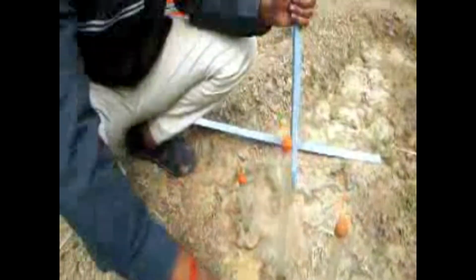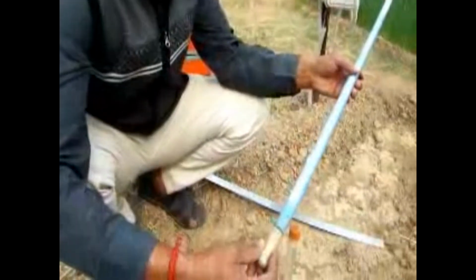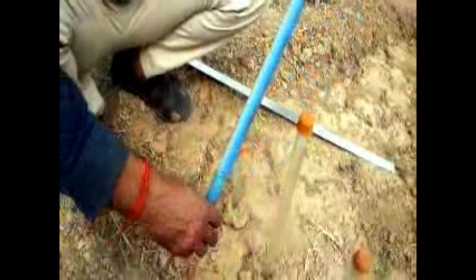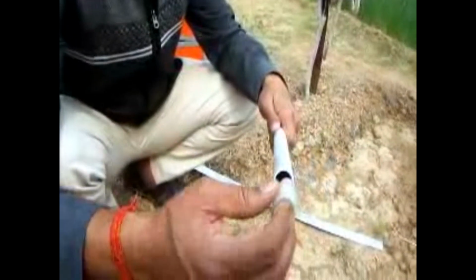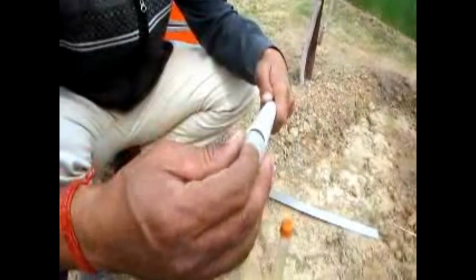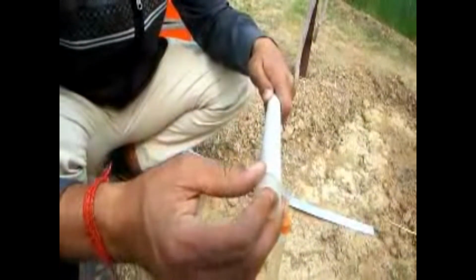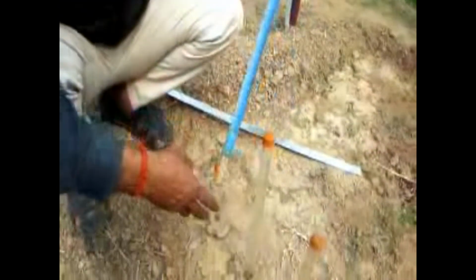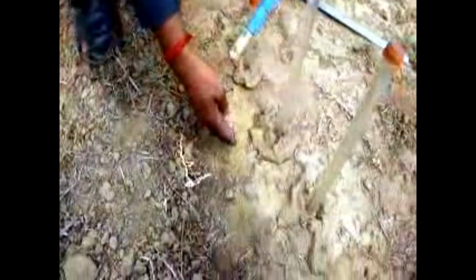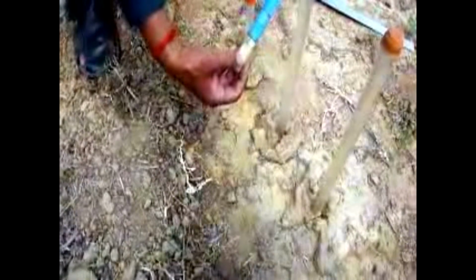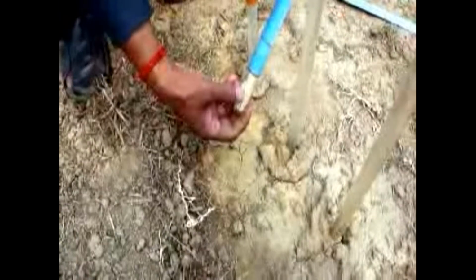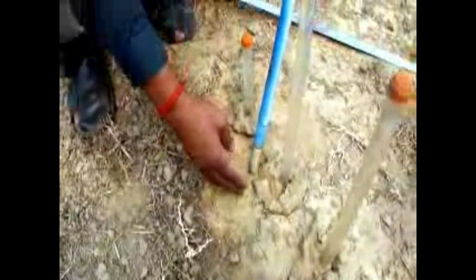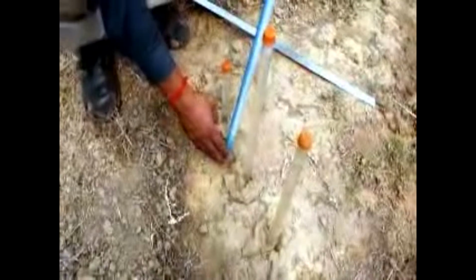What is a tensiometer? You have already learned in your theory. It has a porous cup and a tube. The tube is filled with water, and once it is filled, we put a cap on top to seal it. Because of the dry condition of the soil, the soil tries to exert a suction pressure on this cup, which allows water to balance between the moisture content of the soil and the water inside.